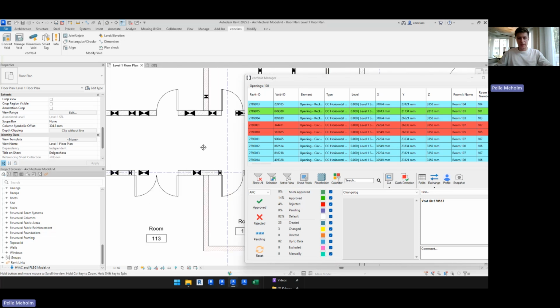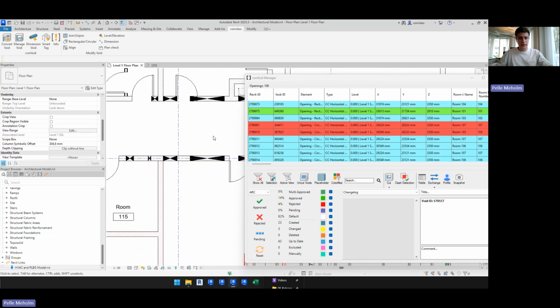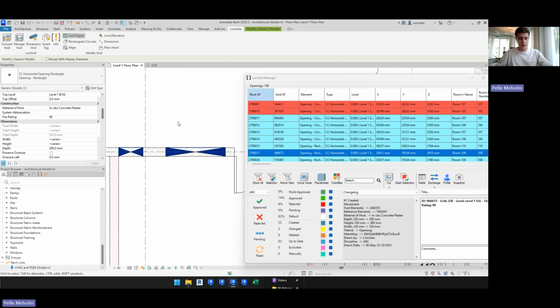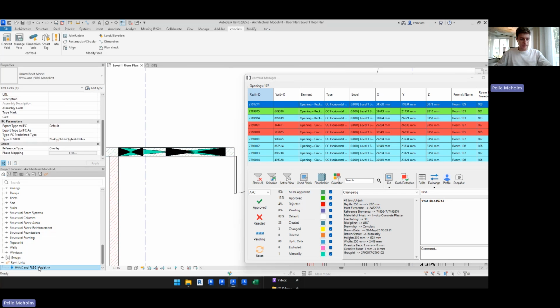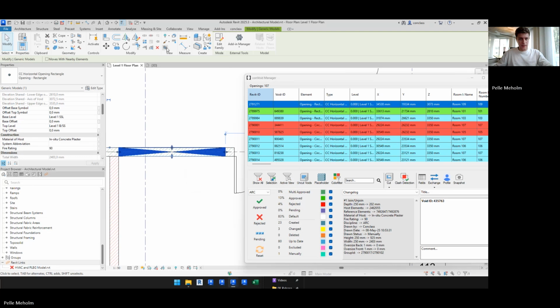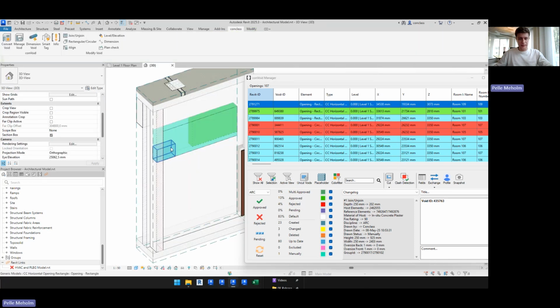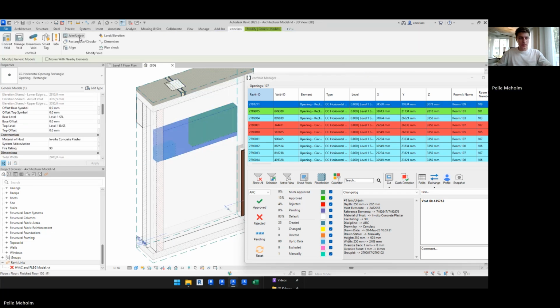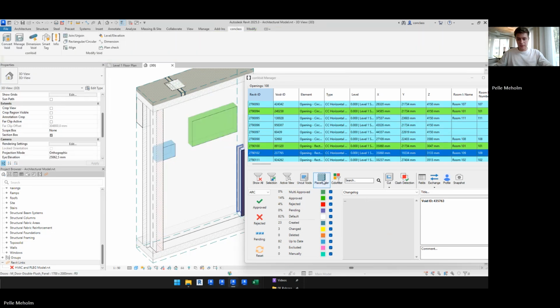This is, for instance, if you join openings manually. Let's join these two openings manually. I'm just going to unload. And as you can see, the openings we used to join the openings are now marked as placeholders. So I can undo that. ConVoid will then mark it as a placeholder, and you still have the possibility to check these placeholders in your ConVoid manager.